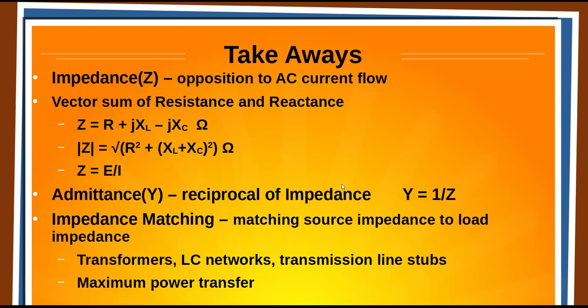The one they don't mention, well, actually, if you've got a dipole high enough up where you might be getting it up to 100 ohms, it's normally 72, depends on height and various things, and you're trying to match it to 50, you could stick a quarter wavelength of 75 ohm in series, which would match 100 to 50.